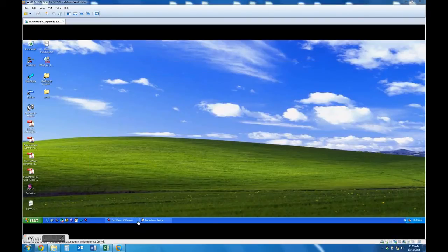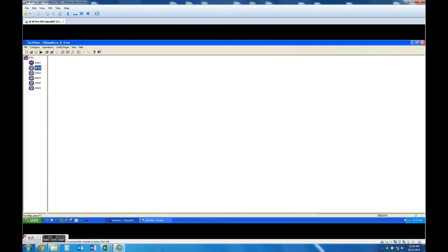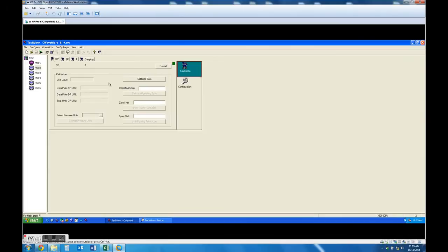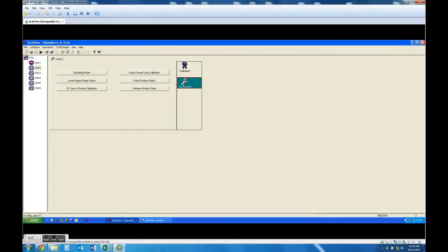TechView. TechView is a standalone OpenBSI software package that allows a technician to calibrate Bristol transmitters either locally with instrumentation or via communications with the transmitter's master RTU controller. It also allows you to perform certain basic configuration operations on a controller, flow computer, or transmitter, to collect real-time or historical data from a controller, flow computer, or transmitter, to perform online edits to lists and archive structures used by an application load running in the ControlWave products.